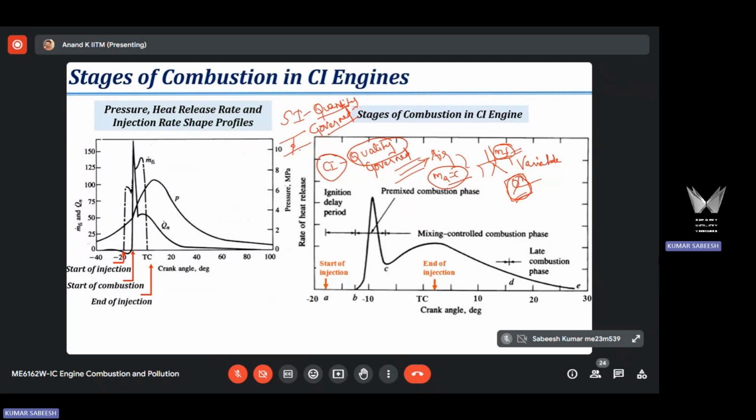The total quantity of fuel and air that enters into the engine is varied by using the throttle valve. Before that, you already have a fixed air mass and a fixed fuel mass. So phi that you fix based on air mass and fuel mass, and the quantity of that air fuel mixture going into the engine cylinder is varied using this throttle valve. That's why it is called quantity. You are regulating only quantity. Here you are regulating the quality of the mixture.